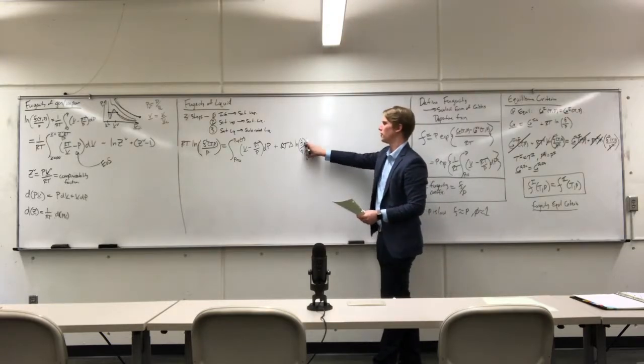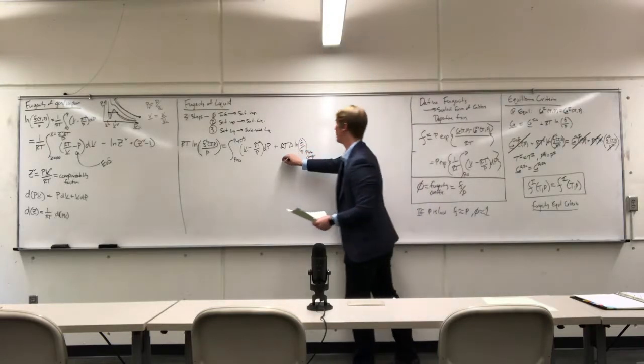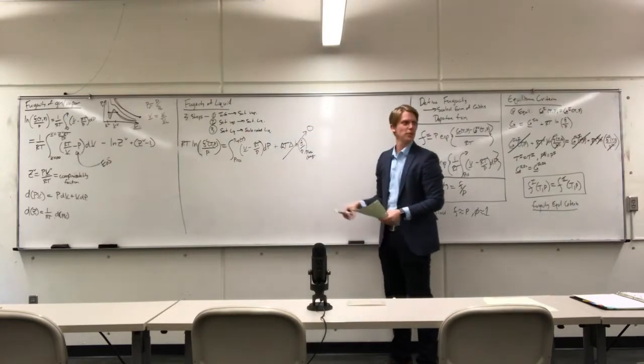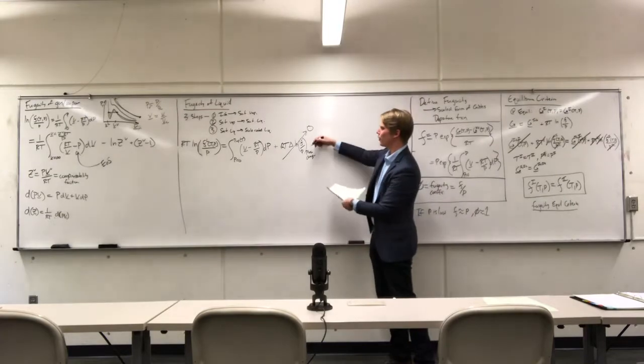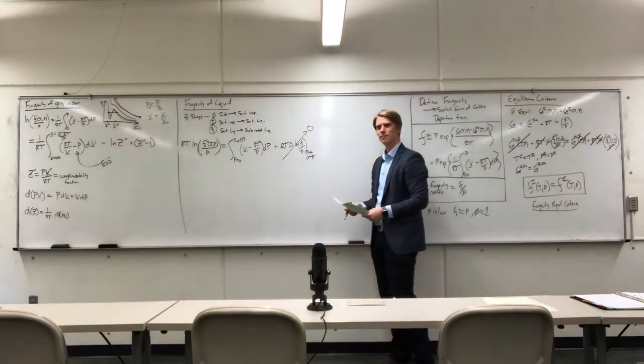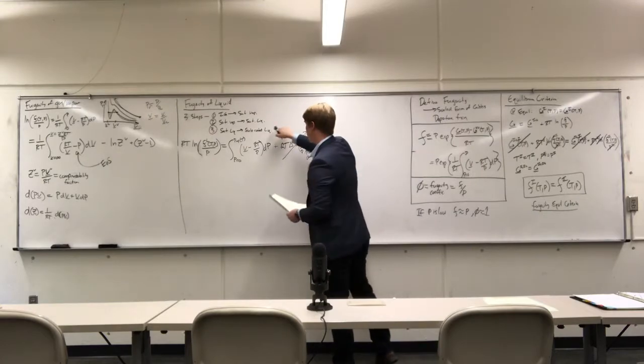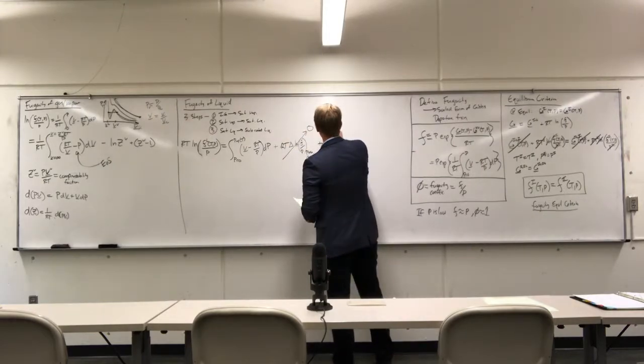The pressure is constant, the fugacity is constant, so this delta goes away. So this whole term goes to 0. And that's why I have kind of a hand-wavy notation there, the delta F over P of a phase change, but it doesn't matter because it goes to 0. The final step is we're going to go from a saturated liquid to a subcooled liquid.